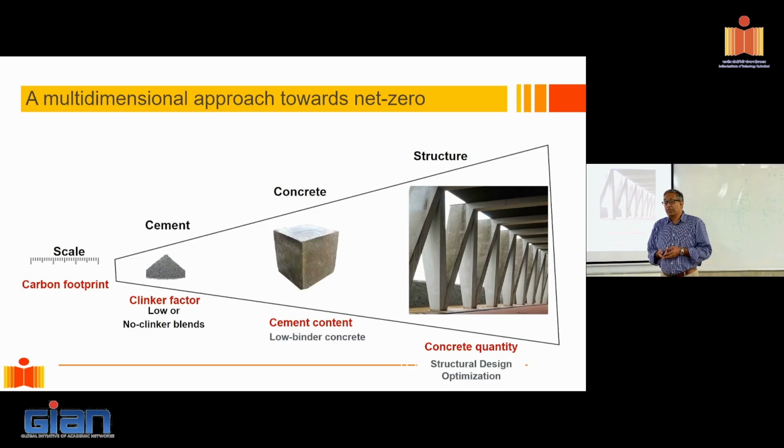and then trying to create cements. What is the objective there? You want to basically reduce your clinker factor, the cement that you're adding in there, right? And why? Because cement is the one that is tagged with the big carbon footprint. So that's what you're trying to do. Scale one, that is the clinker, the cement scale. The second scale is the concrete scale.